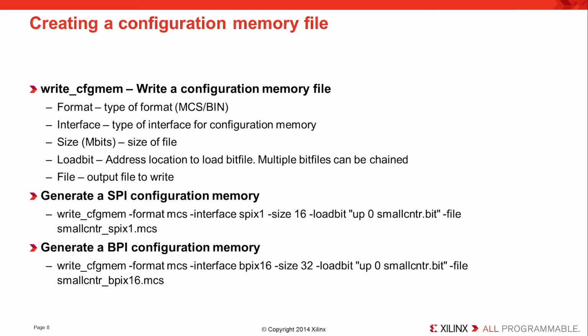Interface. This is the type of interface that is used by your configuration memory. Note if byte swapping is required for the given interface, this command will take care of that automatically for you. Size is the size in megabits for your configuration memory.